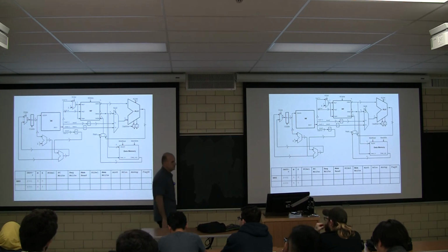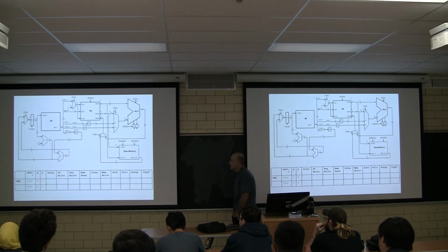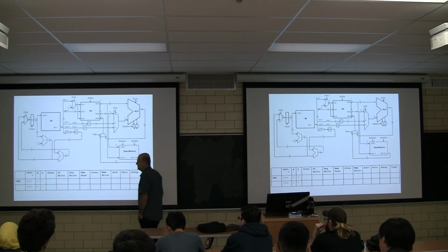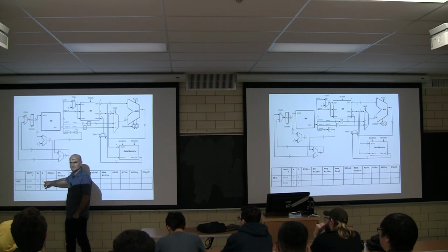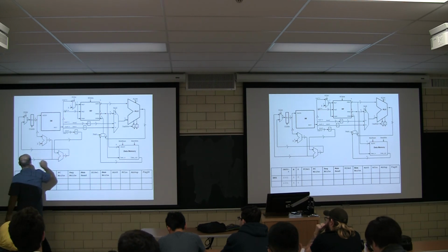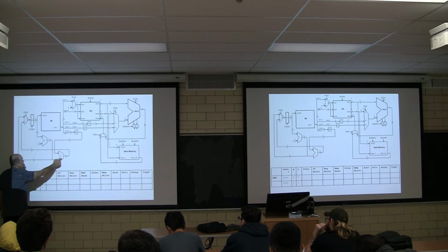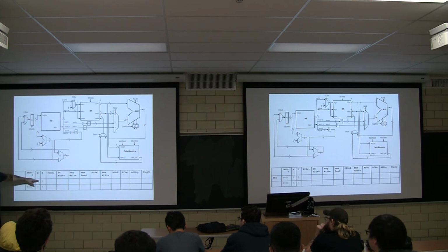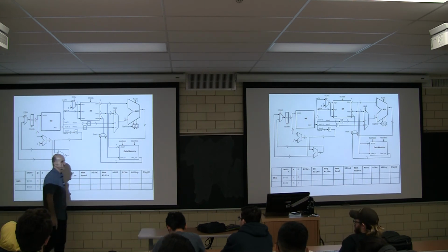Okay. So next question is the following. What should be PC select here? Well, it depends. This is branch not 0. That's the instruction. If the flag is 0, then we want the branch to not be taken. Otherwise, PC select should come from this guy, the taken address. So it should be 1. Here I should write 1. Why? Because this is non-zero. The 0 flag is not true, so the value was non-zero. So this should be 1. Otherwise it would be 0. That's the branch.